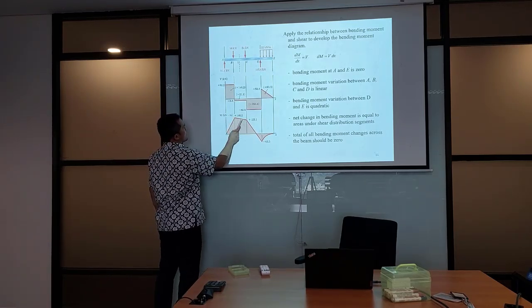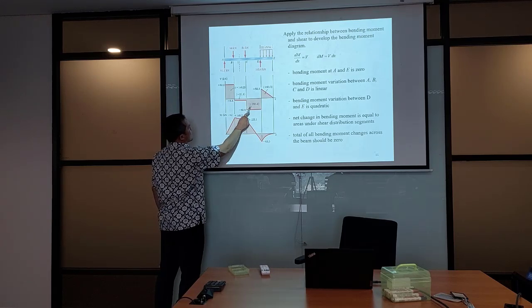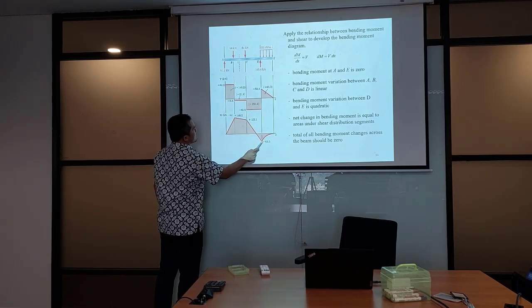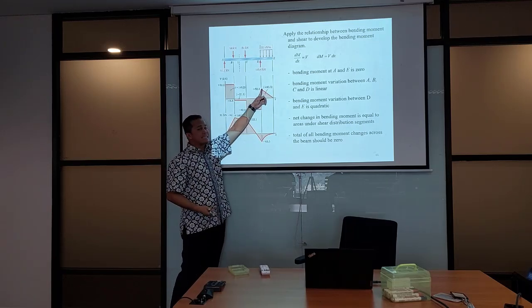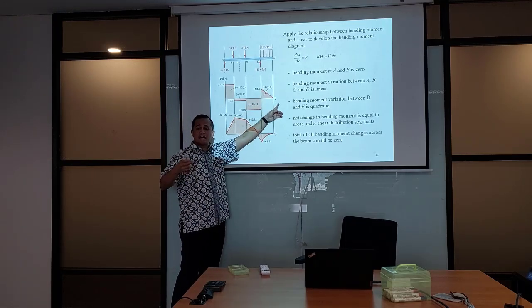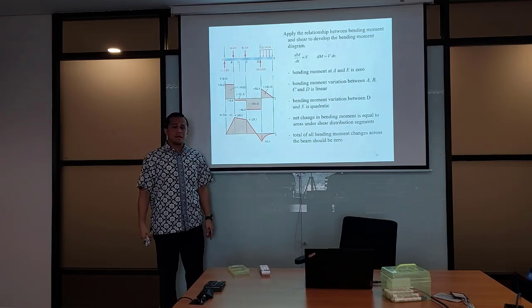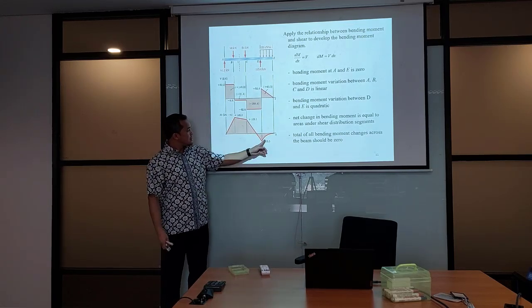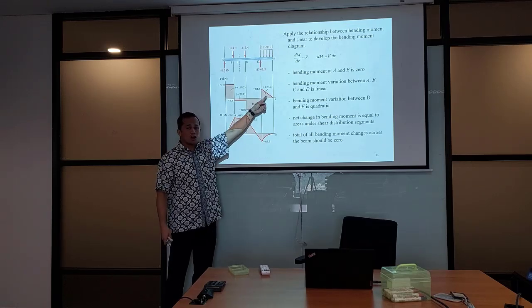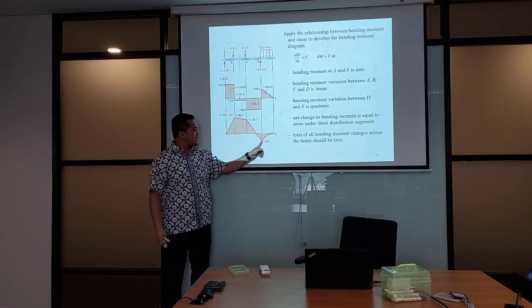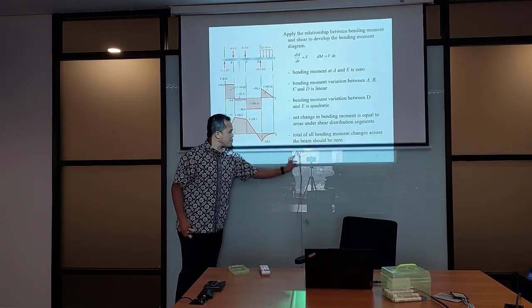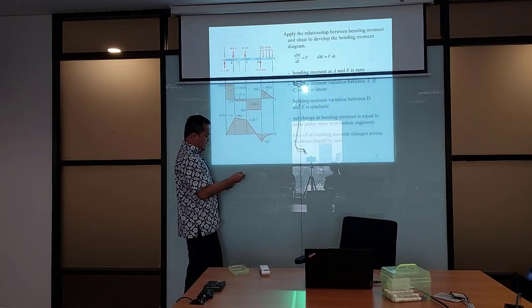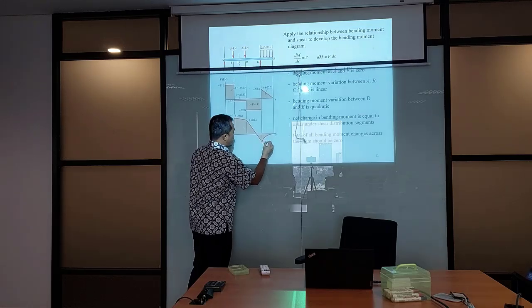146.2 minus 21.1 going downward, another 188.4 going downward, and then this one is the most difficult one because it is a linear equation. When you integrate once, it becomes parabolic. When the slope of a parabolic is negative, it creates this shape, not this shape. When you write the BMD this way, it is wrong.